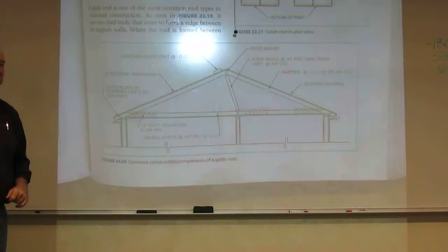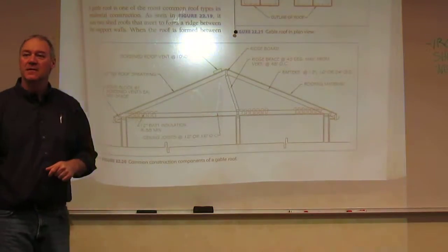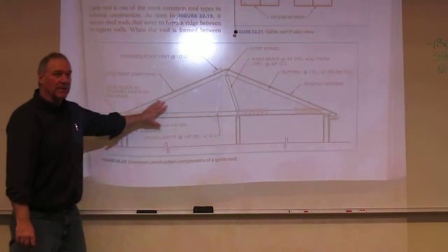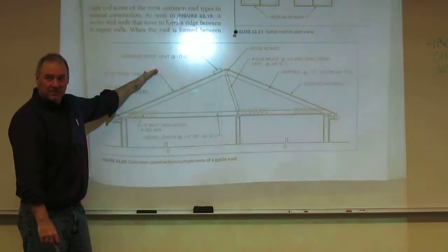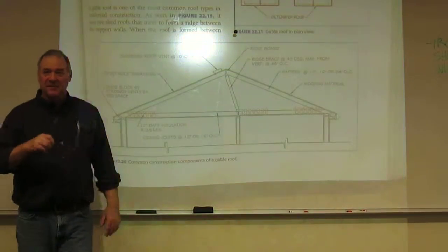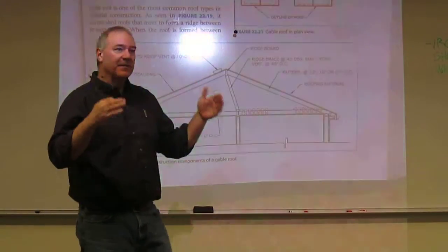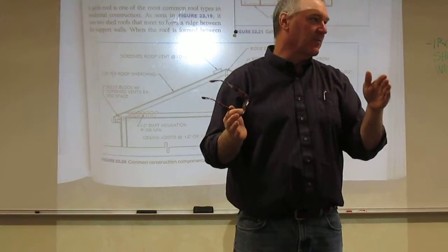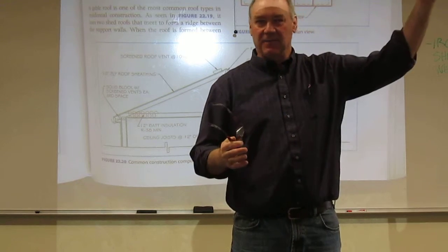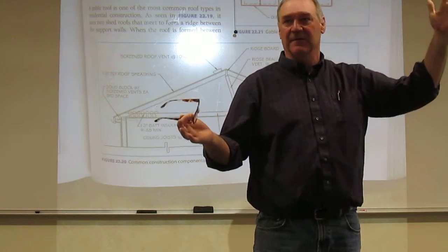In actuality, flatter roofs cost you more because it takes more lumber to carry. The steeper you go, the cheaper they get, except that there's a break even. And it usually happens right around that 6 to 8/12 roof. Those are generally your cheaper ones. And then the real steep ones are expensive, the real flat ones are expensive.